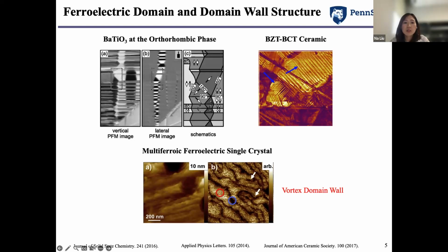In the PZT ceramic system, a very complex domain pattern can be captured because of the many boundaries that exist in the ceramic, giving very complex electrostatic and electromechanical fields. In the multiferroic single crystal, classical vortex domain walls can be visualized using piezoresponse force microscopy.